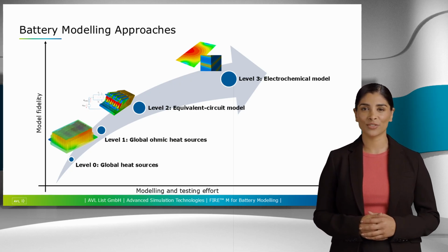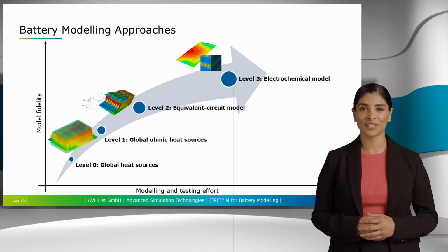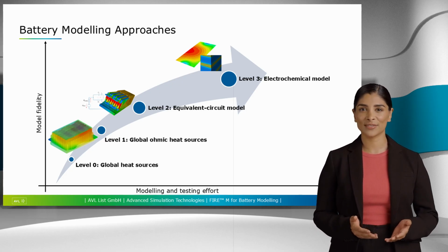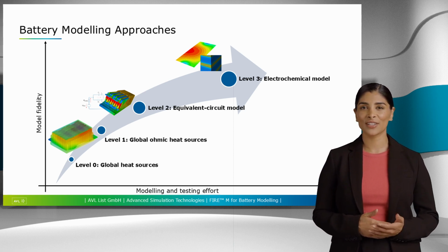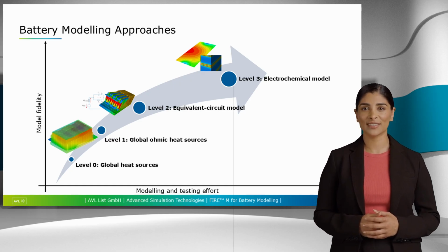The simplest model provides a constant heat output from the battery cell. This is a fast and reliable way for initial simulations in an early development stage, when not much of the layout is fixed yet. If the heat dissipation depends on the internal resistance of the battery and the electric current, the model is still of low complexity, but it allows the investigation of simple load case scenarios.